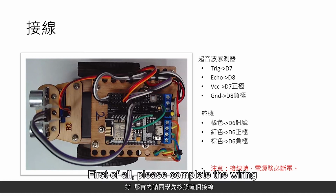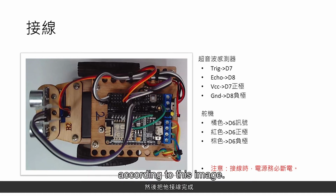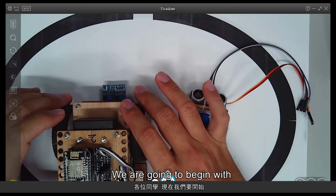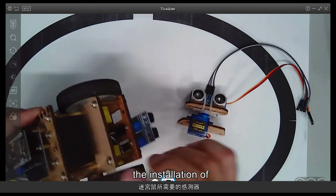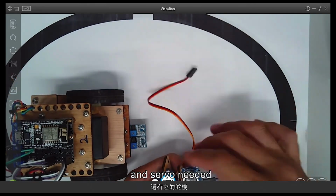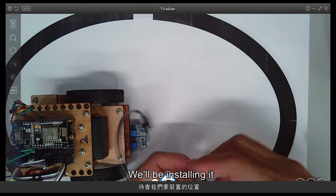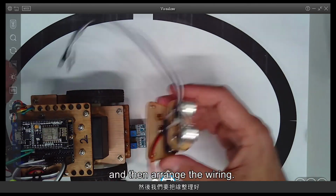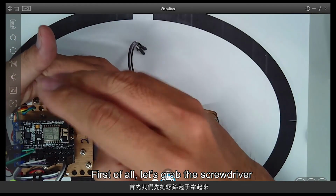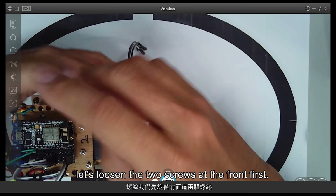First of all, please complete the wiring according to this image. During wiring, please ensure that the power is cut off. We're going to begin with the installation of the ultrasonic sensor and servo needed for the maze walkthrough. We'll install it in this place, and then arrange the wiring. First of all, let's grab the screwdriver. Let's loosen the two screws at the front first.